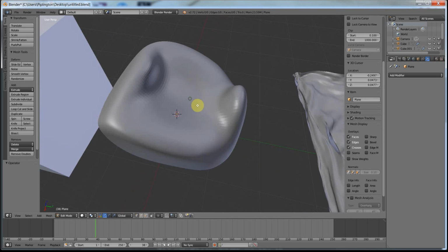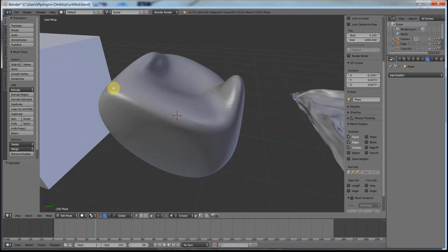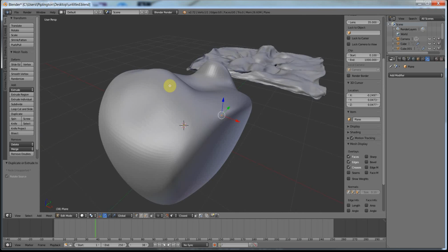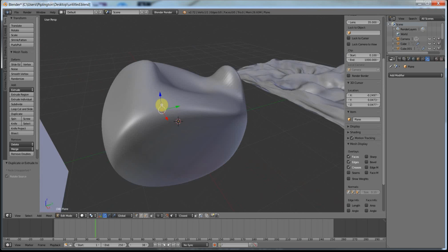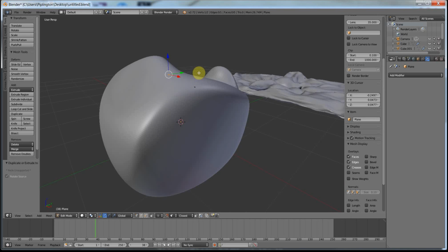So what I'm going to do is put it on snapping to faces, so the face of this object, which means that when I press on the corner here, like I know I want the shape, so I click there, and that point is now stuck to the surface of that, which means I can put another one here, and it's not followed the exact shape obviously because we've only got 2 points for it to go through, but